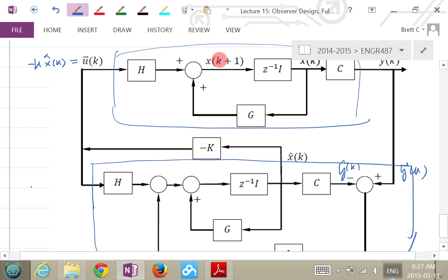So in order to generate the U, the voltage input, your U is based on feedback from the observer output. And the observer output gives the estimation for every one of the state variables. That's why I use K times this x hat. That make sense?